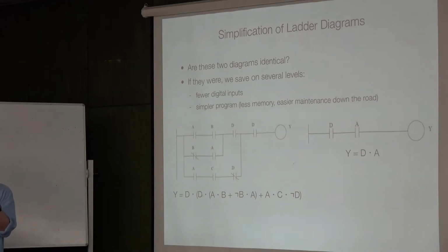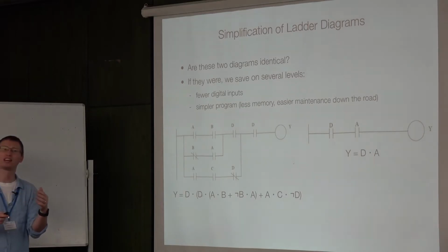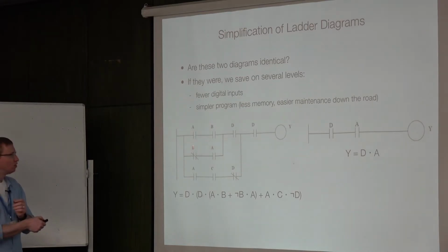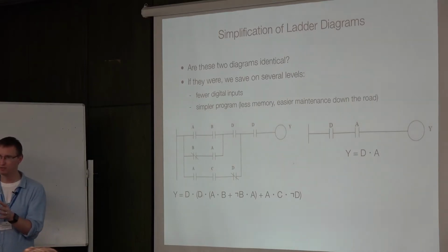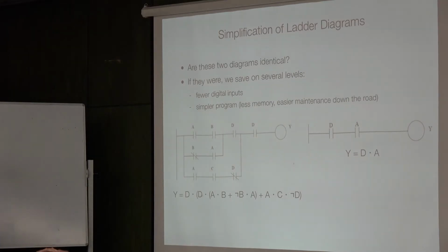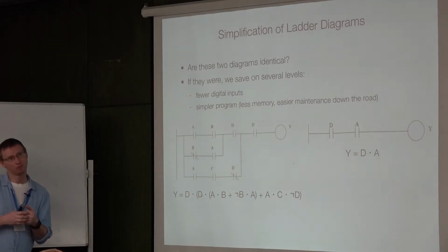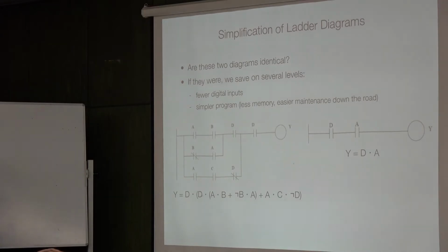So I guess what you mean is that when one input would influence the other one, you can get a non-deterministic behavior of the system, something along those lines. But here those values of the inputs are fixed. Whenever they are read into the PLC to execute the program, their values are fixed. So there is no influence of these sensors on each other. I was talking just about race conditions. Might be, but again, this is fixed by keeping everything constant at the start of the program loop. Okay.